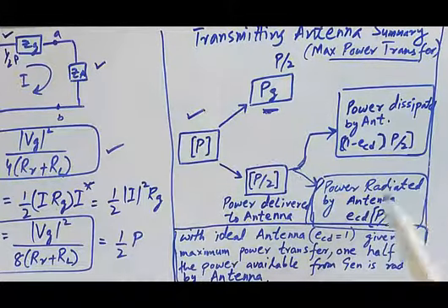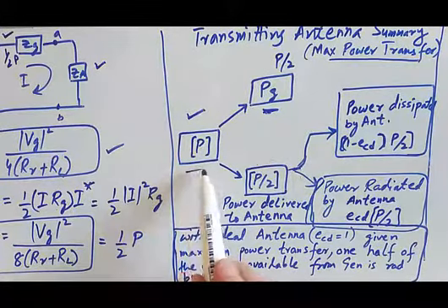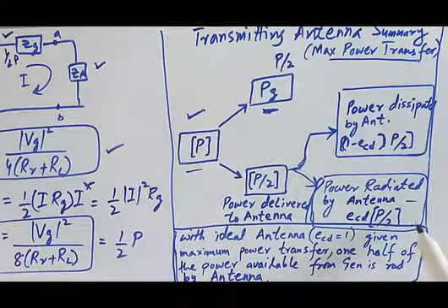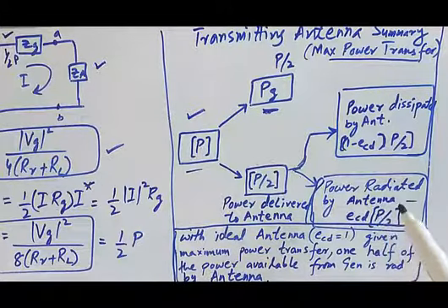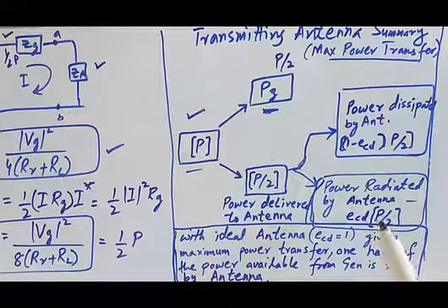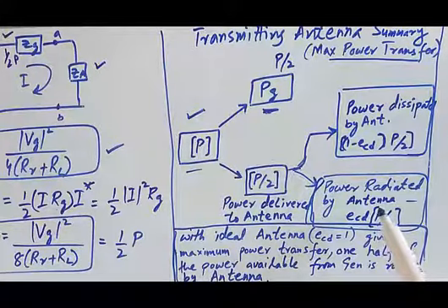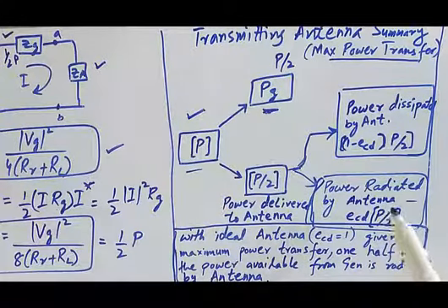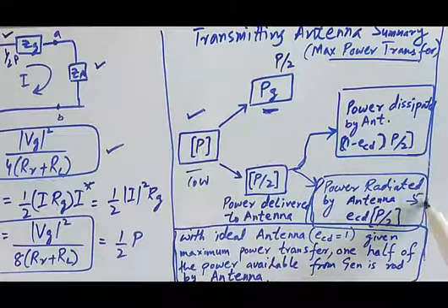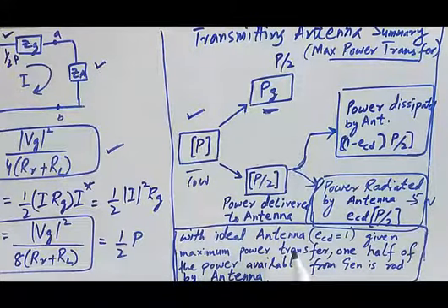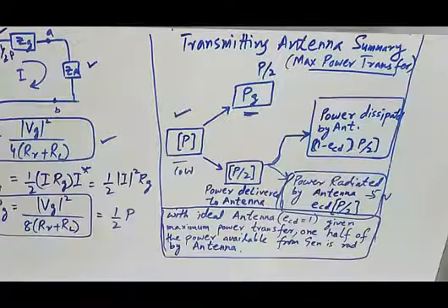by the antenna. It means that initially we have, for example, 10 watts, then 5 watts is going to be radiated by the antenna, and the rest are actually the losses, and those losses are not the losses of antenna efficiency. In fact, I am considering antenna efficiency at the moment, for example, equal to 1, then even then the 10 watts is going to get reduced to the 5 watts over here, okay. So what I can say is, with an ideal antenna where ecd is equal to 1, given maximum power transfer, 1/2 of the power available.